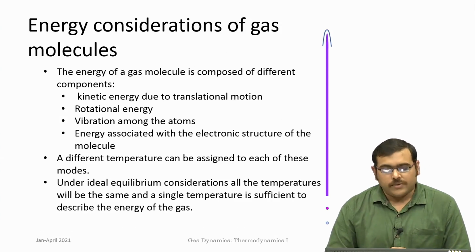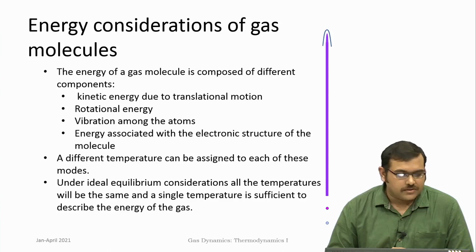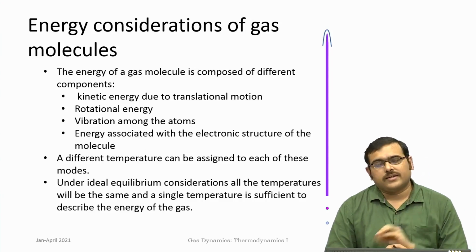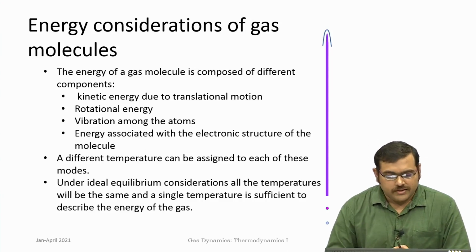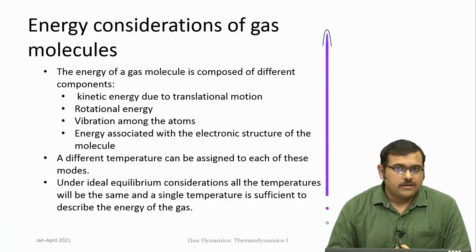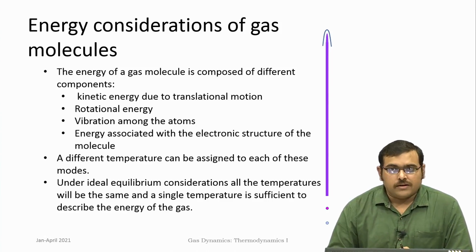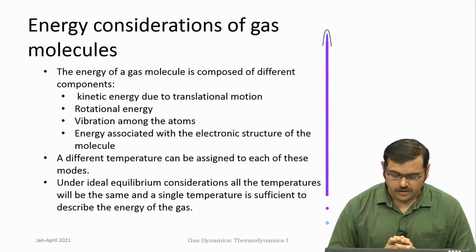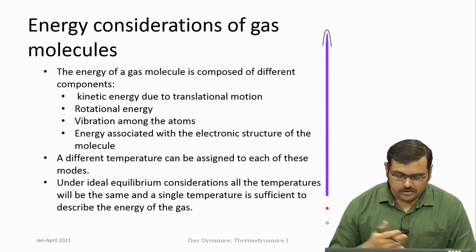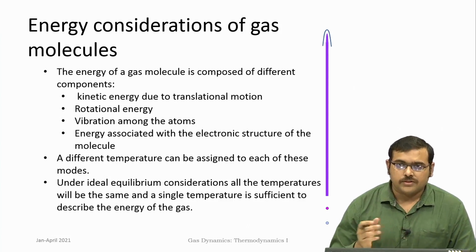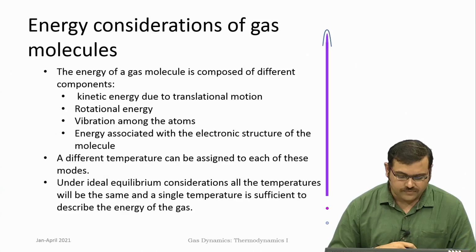What we call temperature is actually related to the energies in these different modes. If you consider each mode separately, then a separate temperature can be defined for each of these modes, but we do not normally do it because we are considering ideal cases where we have a lot of molecules and they collide with each other, and the energy distributes uniformly among all these different modes.